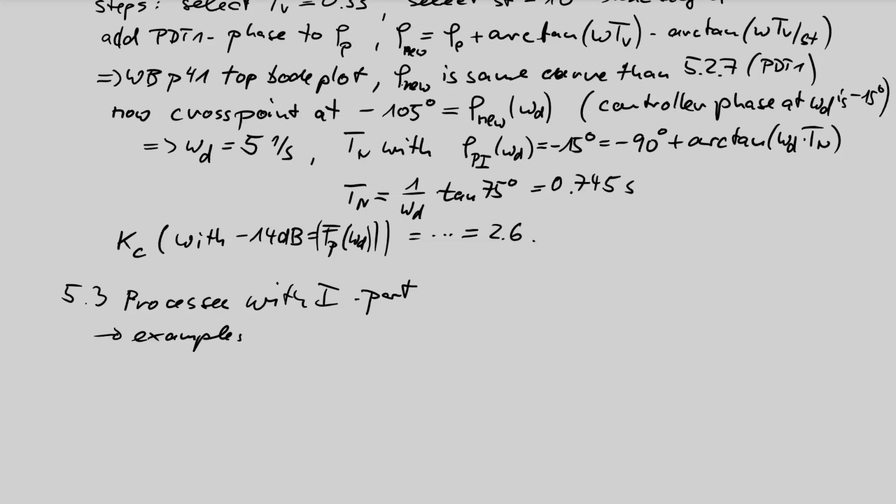We will have this. One we have learned, level control. We have a tank level control system. In chapter 2, which we have analyzed, the level of a tank depends on the input and output flow, and the level directly can be calculated from the integrating of input minus output flow. So we have an integration in the process.